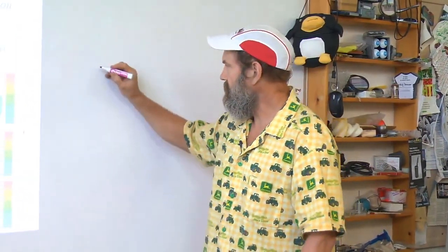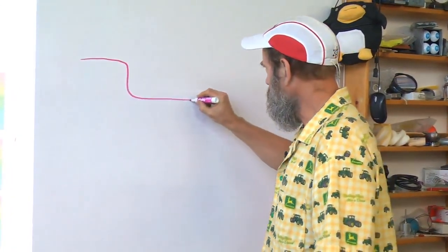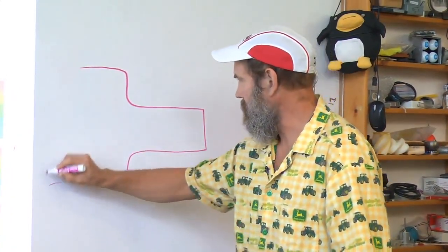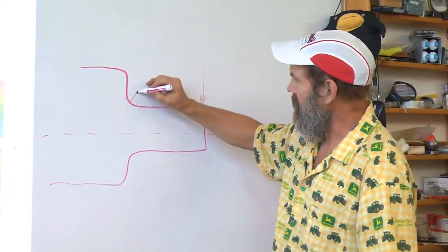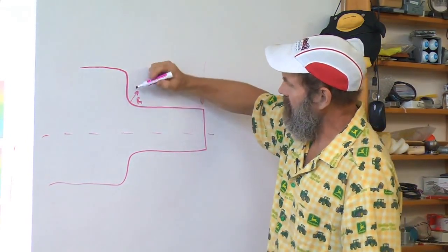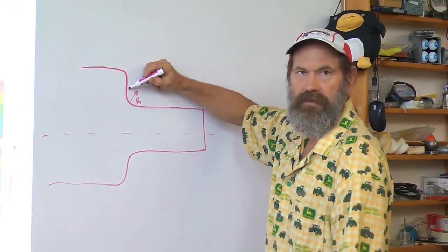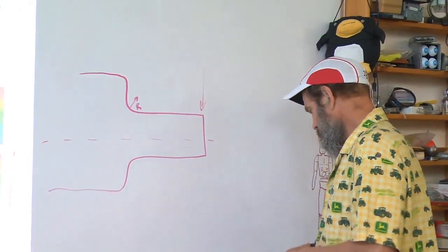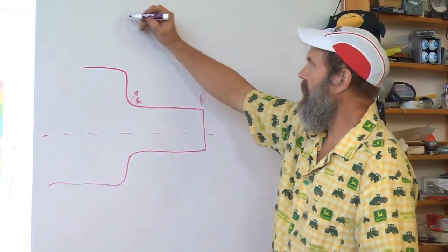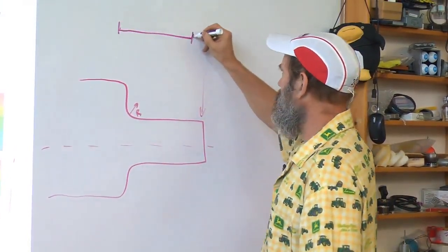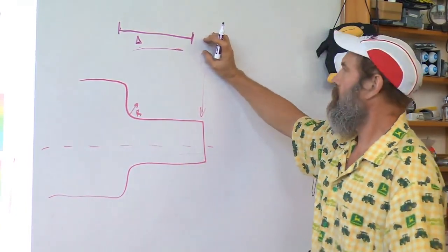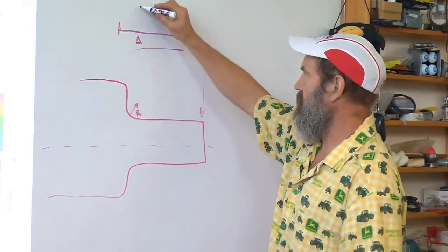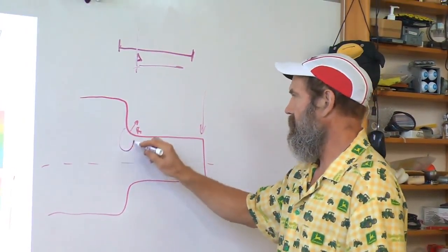What I would do is, in a typical part of the structure I'm analyzing, let's say I have a shaft I've created, applying a load, and I'm trying to investigate what size radius on this fillet I need. In the finite element program, typically you have a little slider scale that you can drag for the fineness of the mesh. You would start with whatever the default is, and you would get what the maximum stress is.